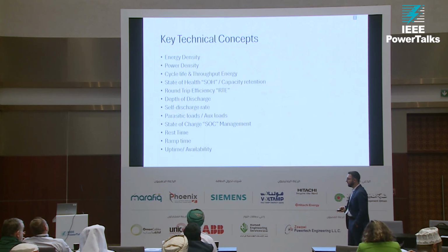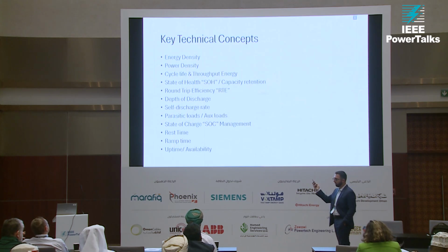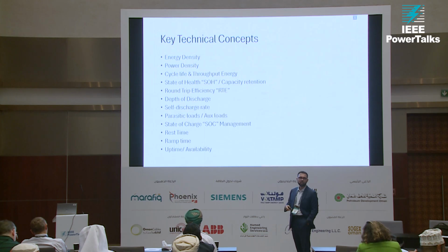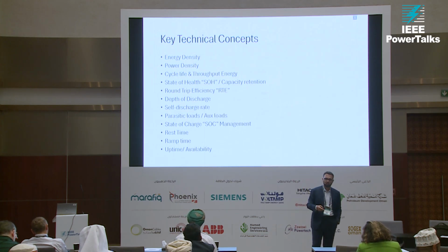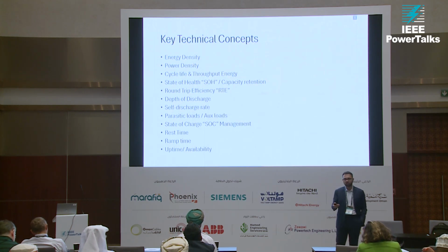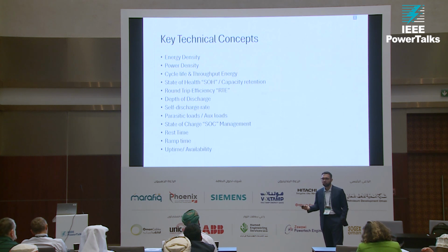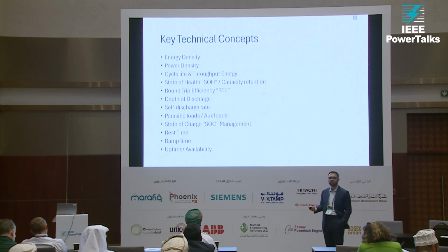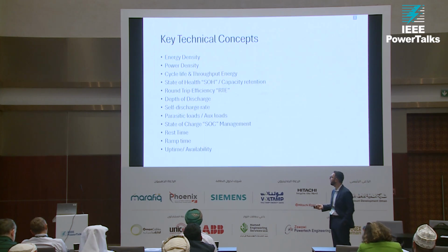So ramp time is how fast the battery can go from 0 to 100 or 100 to 0 or anywhere between. Each battery has its own characteristic. For example, thermal energy, it's not that fast. It's anywhere between 10 to 15 minutes to ramp up. Pumped hydro is somewhere around that 10-minute time frame. When you talk about electrochemical energy, it's 2 to 2.5 milliseconds that you need to go full from 0 to 100 and 100 to 0 from a power ramp-up standpoint.